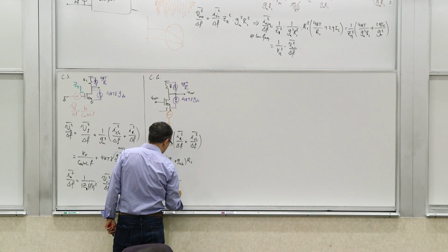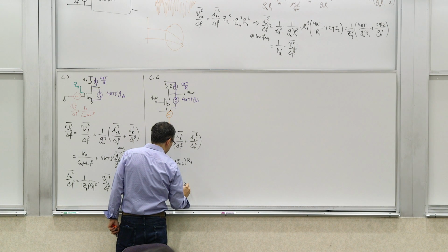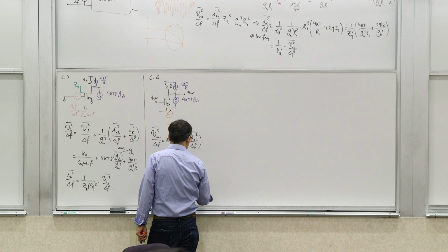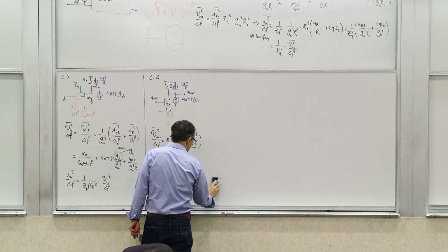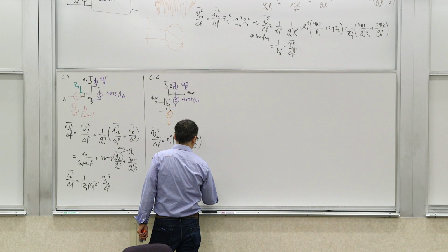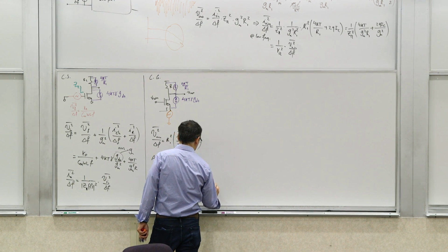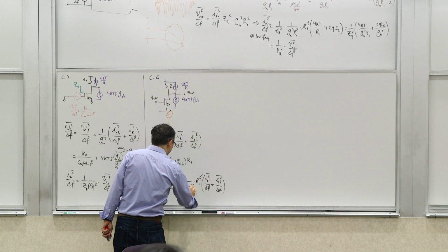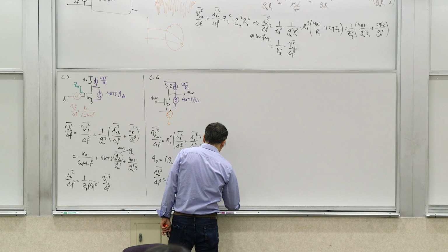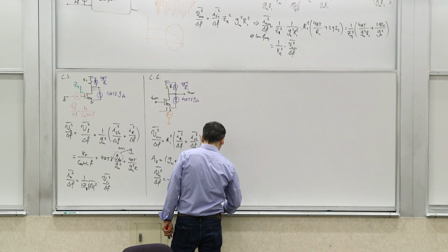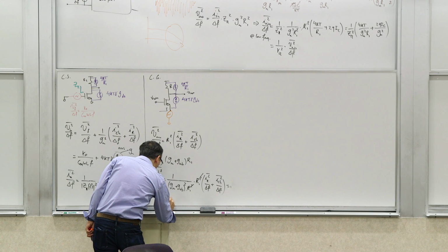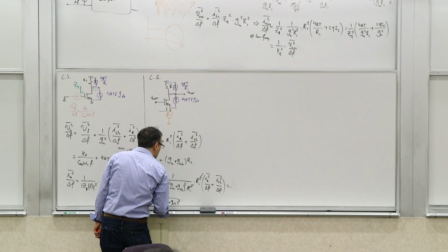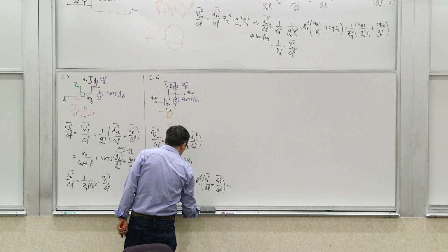So it would be 1 over (gm plus gmb) magnitude squared, times R1 squared, times those two terms in the parentheses, which is I_R squared over delta F plus I channel squared over delta F. And these R1 squared terms cancel, so what you're left with is 1 over (gm plus gmb) magnitude squared times the values of these things. You can plug them in.